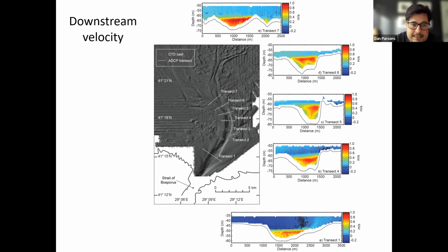Now, what happens in the Black Sea, that we discovered both from the modeling and then also from our field data, is the reverse happens in these submarine channels in many situations. And that is because the flow is being driven by the bed, the greatest outward force of that acceleration force as the flow enters a bend is near the base of the flow. And that means that the fluid at the base of the channel moves outwards and the return flow is near the surface. So the helical flow that goes around a submarine channel bend is inverted compared to a river channel.